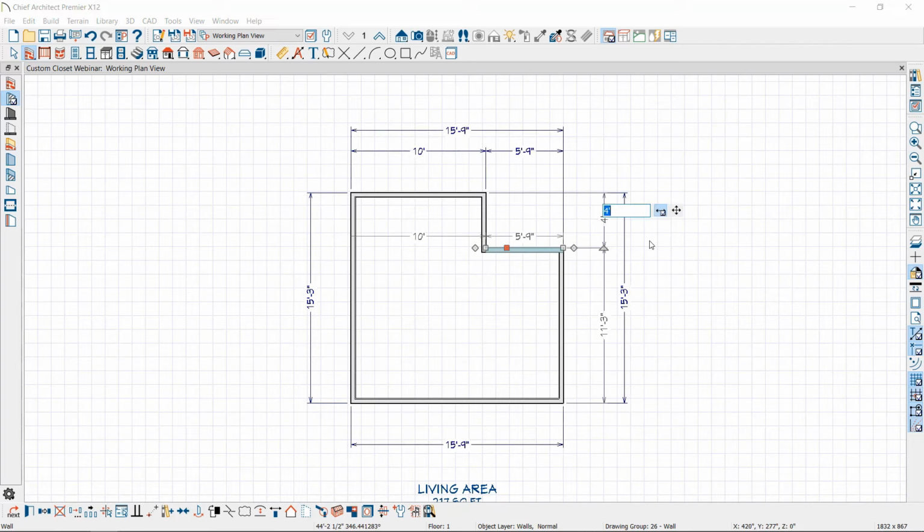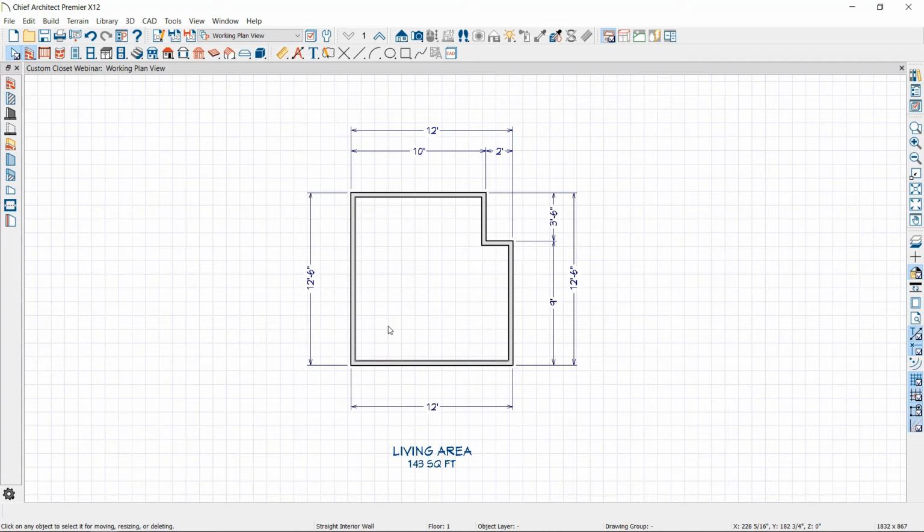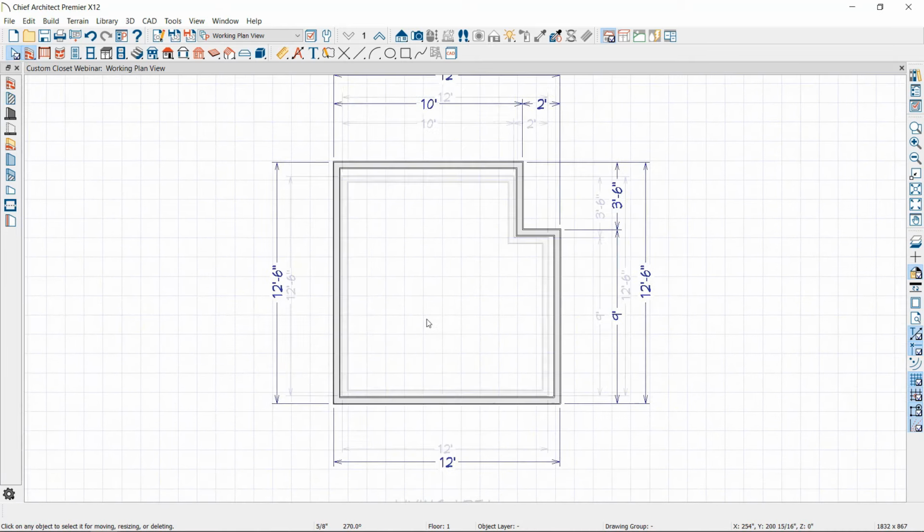So I'm going to select its perpendicular dimension, and type in 42 inches, hit enter, and I'm just going to go around the length of this room. So here we're going to select this wall. I can also do in feet, so I'm going to do just 12 feet and hit enter. And I have just one remaining dimension. So I'm going to select this wall, select the perpendicular so I can say how far it's going to be from the first wall that we started with. And I'm going to say 150 inches. Hit enter, and now I have my space dimensioned.